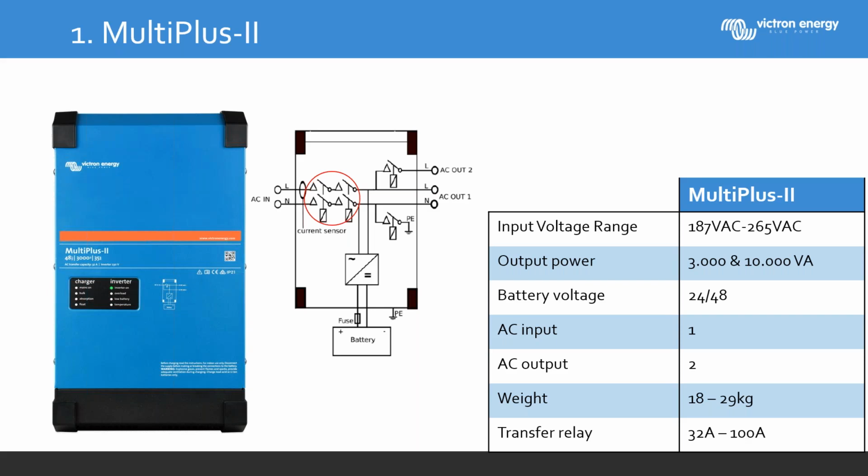applications as well. The range is now 3,000, 5,000, and goes up to 10 kVA. At the moment, the 8 and the 10 kVA are not compatible for parallel systems, but they are compatible for 3-phase. So 3-phase meaning 3 units, 1 per phase. So 3 times 10 is 30 kVA. You cannot add any parallel units at this stage.